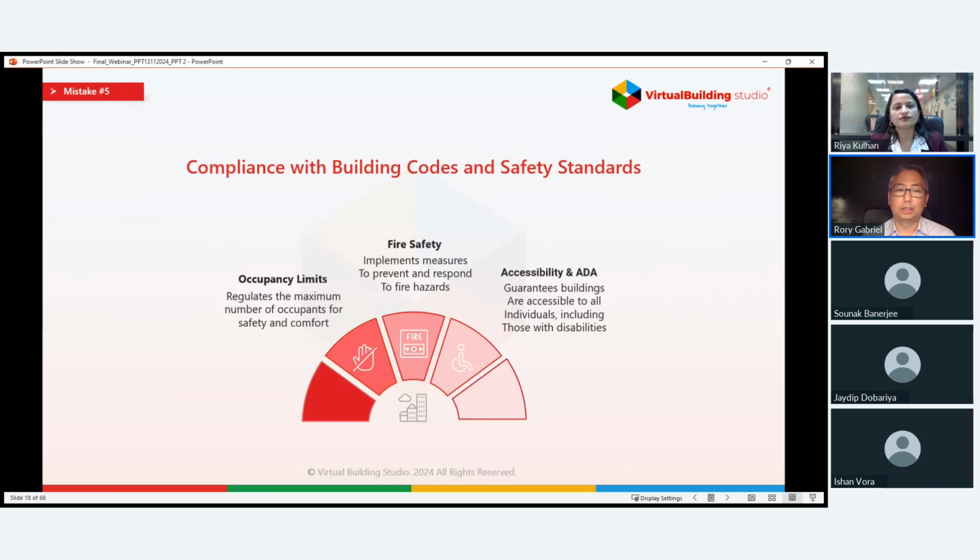Another issue, life safety, is incorrectly drawing the egress path. Sometimes using the most direct route, a straight line from A to B, instead of accounting for how a space could be filled with furniture or equipment, and how an occupant has to move around that.